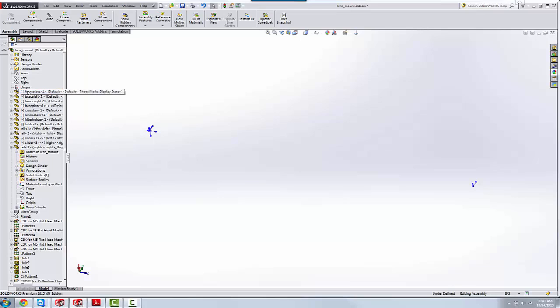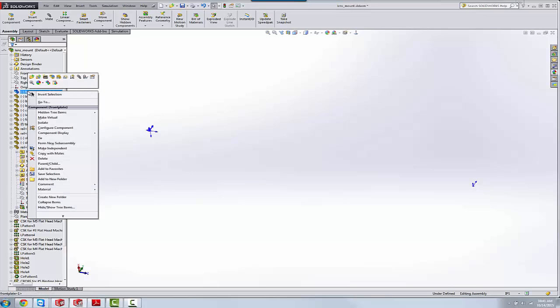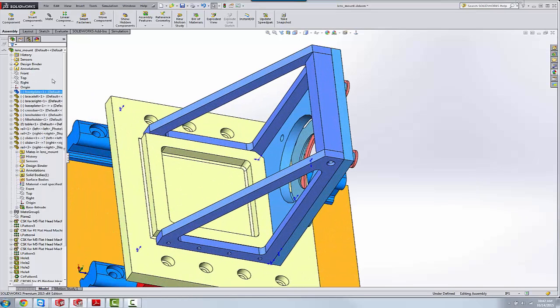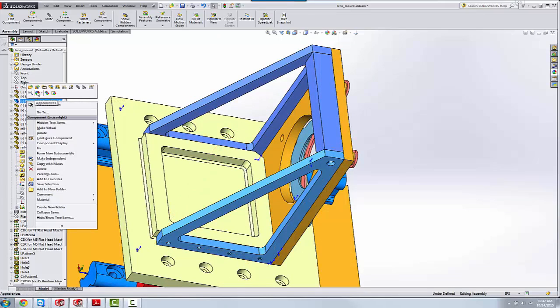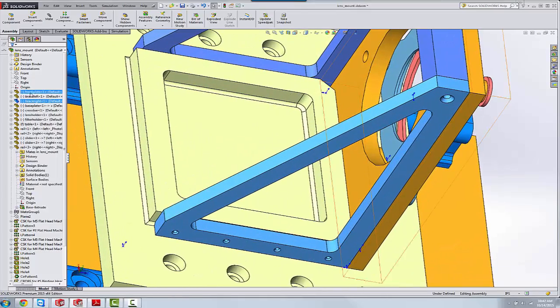The first thing I like to do is take some of your original components you added and do a zoom to fit, a zoom to selection rather. You can right mouse click the little equal sign here. It'll almost always come into view if this was something that you did towards the end of the design. So zoom to fit, and all of those show up.